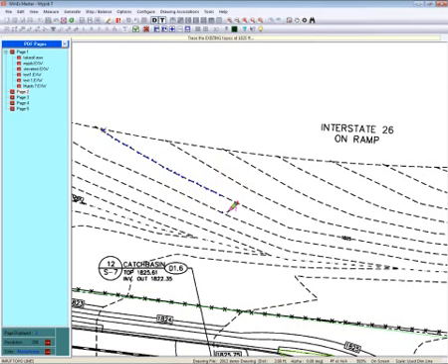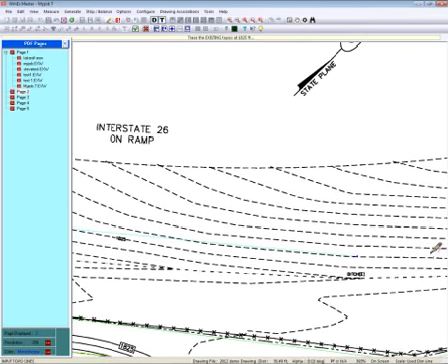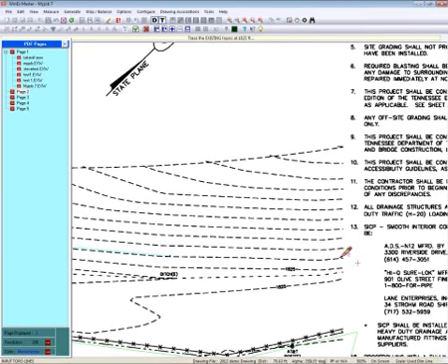So when you do get an error like that, it's very, very simple. All you do is hit your backspace key, and that'll take you back to the dot just before you made that mistake, and then you can continue on as though nothing happened. And again, when you get to a straight area, all you need to do is click on that area. By the way, notice as I get to the end of the page, the pencil, if you have our nudge feature turned on, will automatically move the page over a set percentage that you can set.